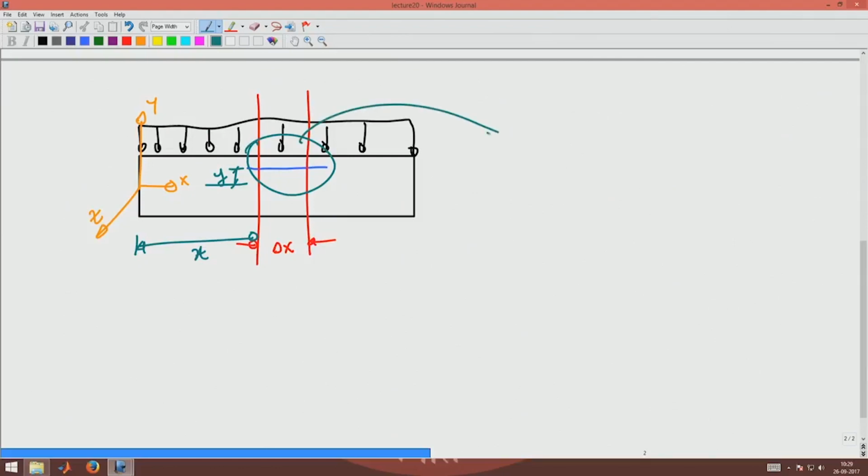This cut section I am drawing it here. Okay. So, basically what I have is these vertical lines cut here, then I have the blue line cut here. Okay. And there is some loading acting on top. Since I am assuming that the beam is bending like this, there will be compression on the top face.